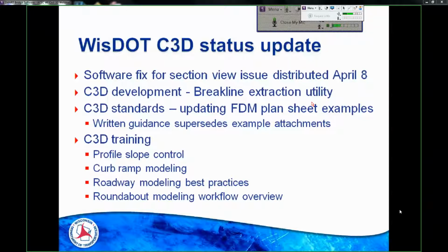It chases all of the things that define that surface all the way back through the Civil 3D project data to source objects. And then, if it was a corridor, it extracts the feature lines that were used in defining that corridor surface that was put into the refinement surface. It extracts all those break lines and puts them in a separate file that ultimately becomes your break line file.